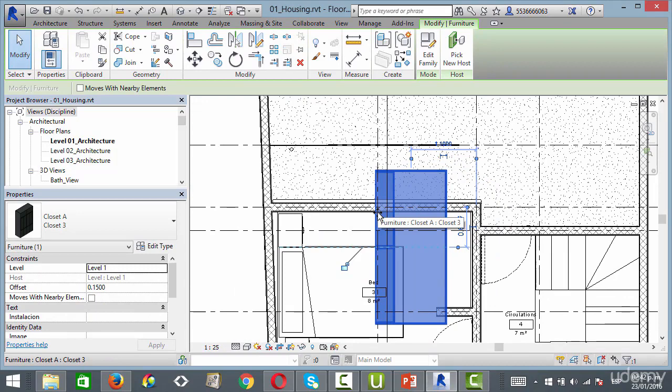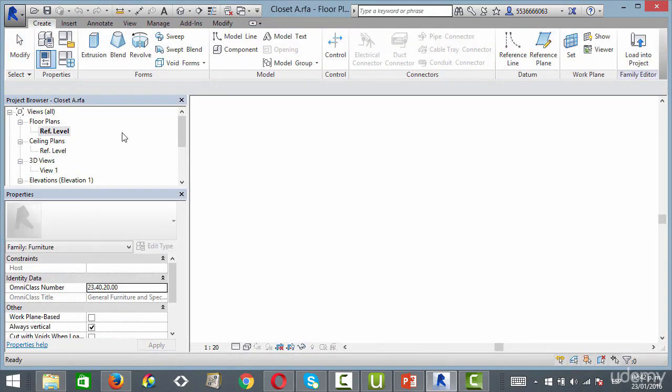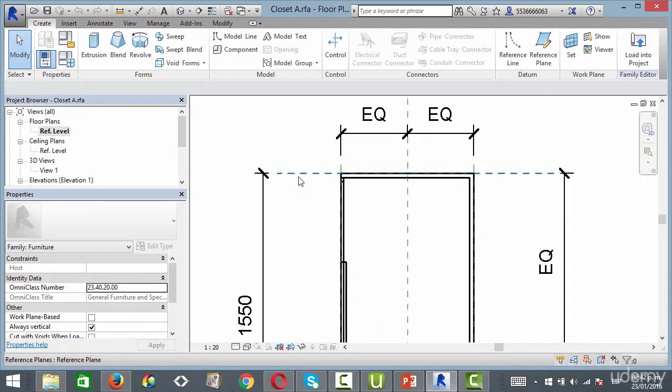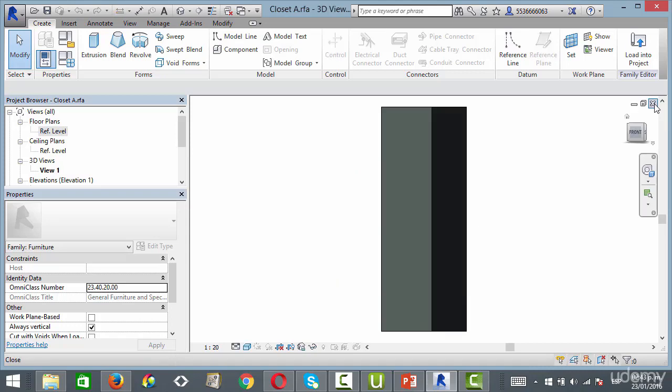But be aware, since they may ask you to check if the family has already been done properly, so you may need to edit it to check if the parameters respond, or if there are some parameters that aren't unlocked or have some problems. So I believe that if you know how to create families, you won't have any problems with this topic.